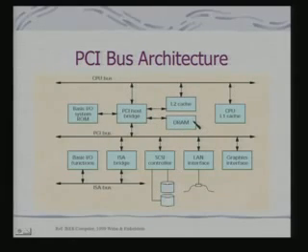We have already studied that DRAM is a slower device, and the CPU bus will be pretty fast because the CPU is working at a higher clock rate. So, the PCI host bridge provides the communication interface between the fast CPU bus and the slow DRAM device. It also provides connectivity to the basic IO system ROM as well.